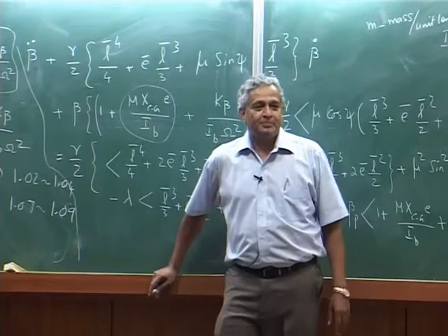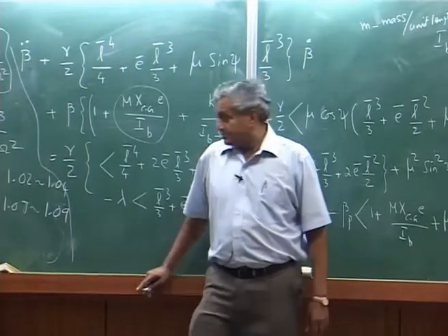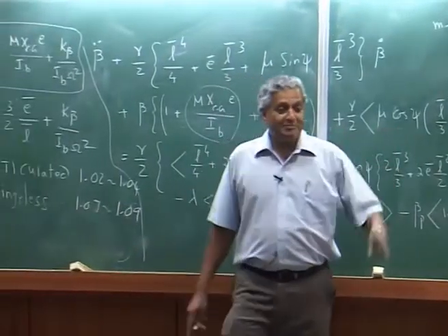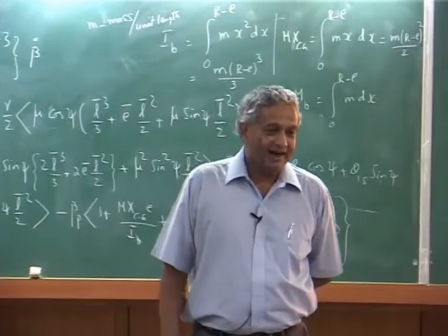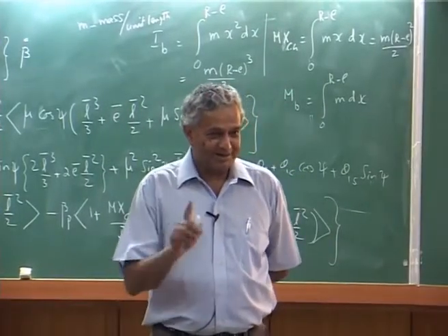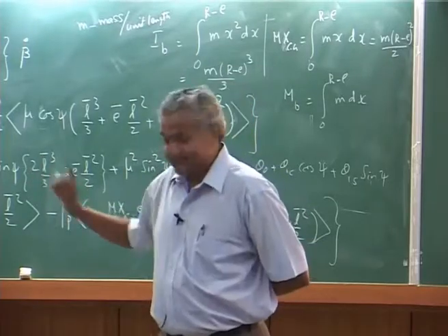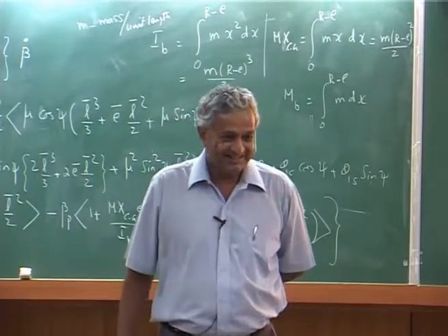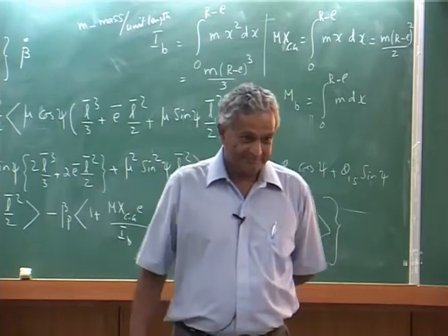Plus, what is the control moment affected by? The flap frequency. You remember Cmx, Cmy, that expression was what? Omega bar Rf square minus 1 divided by gamma by 8. Omega bar Rf square, if it is higher, you get a higher moment, right? Higher control moment you get.